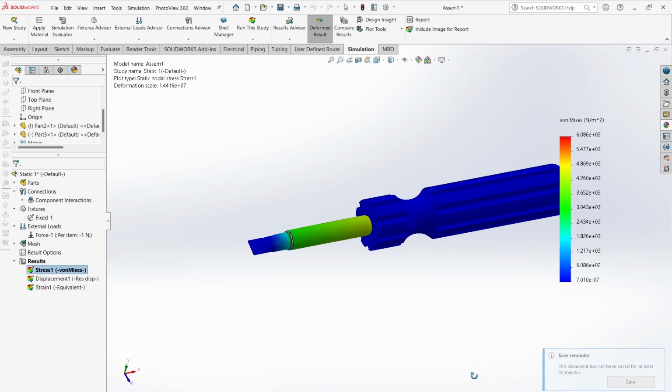So see, we got the stress. This is the value of the stresses, and this is a visual representation. What I did is, when you place a screwdriver against a screw with a force, what will be the stresses generated on the body that I have calculated? If you place it with 1 Newton, then these are the stresses generated. Blue areas are the least stresses, red areas are the maximum stresses generated. Then displacement, the maximum displacement will be happening towards the knee, and this is about the strain.